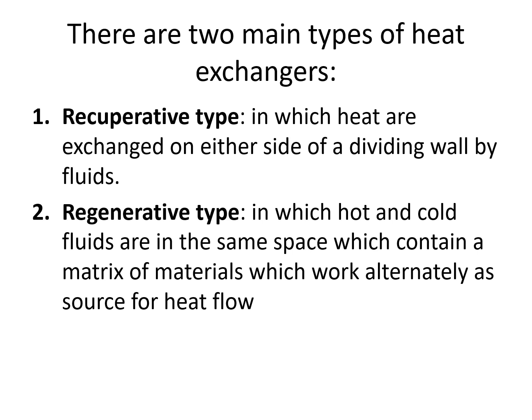If you see, there are mainly two types of heat exchanger, called recuperative type and regenerative type. So what is recuperative type? Recuperative type means the heat exchanger in which there will be a wall between both the mediums, and they will have their individual environment to work in. For example, shell and tube or plate type heat exchangers, or even a reactor which has a coil, they all are recuperative, because the heating medium and the cooling medium stay in their own environment, in their own pressure behavior. But when we come to the regenerative type, both the cooling medium and the heating medium come into the same environment.